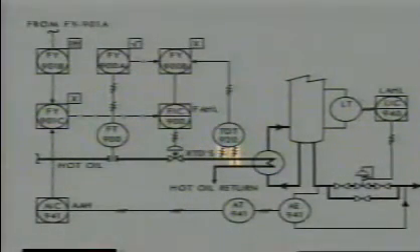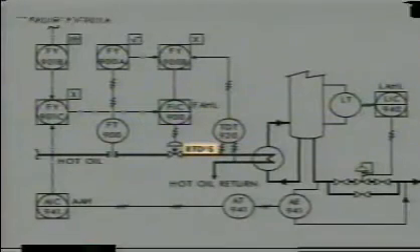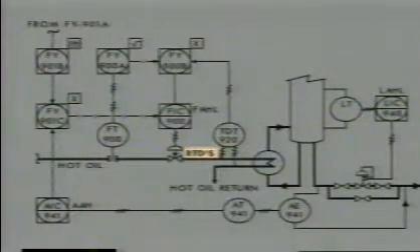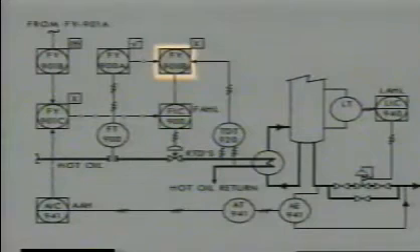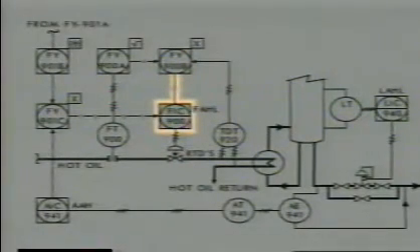This transmitter has two electrical inputs from the temperature sensors. This note identifies RTDs as the temperature sensors, so RTDs provide the input to the differential temperature transmitter. So the differential temperature transmitter sends a signal to computing function 900B. As we said, this is a multiplier function, and the product of its inputs is sent by this data link to the set point on FIC 900.